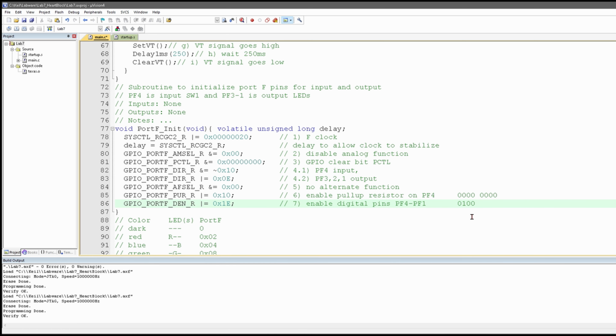If we AND these together, well, nothing's going to happen, right? They both have to be 1 for this to work. If it's an OR, though, it'll set it no matter what. Now, if this is a 1, and we AND it with 0, it's going to clear it. So AND is typically for clearing, and OR is typically for setting.